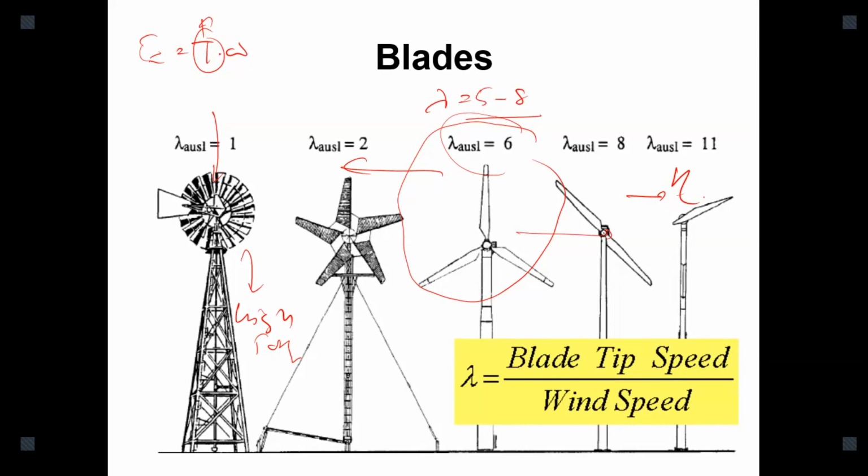Then there is the top part of the large wind turbine, the wind rotor and nacelle. Generally, it can rotate to orient to the wind direction. Orienting to the wind direction, we call this yaw action. Yaw is done for large wind turbines from time to time, within some time period, maybe 5 minutes or 10 minutes, depending on the manufacturer. After detecting the proper wind direction, the wind turbine yaws to the proper wind direction.